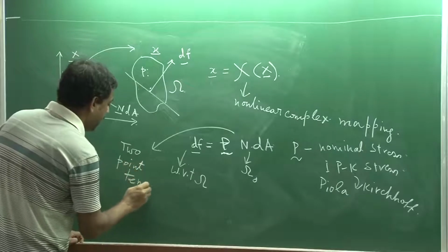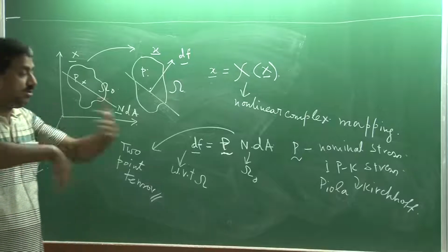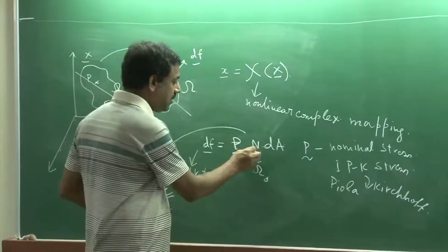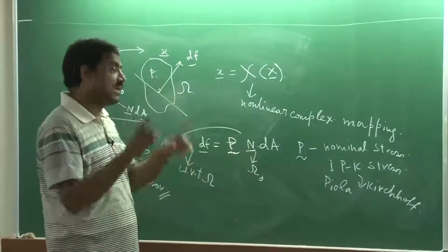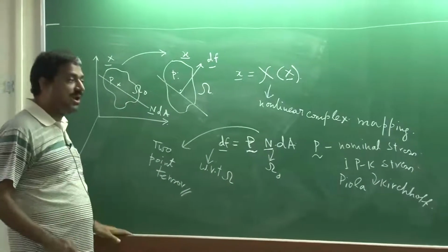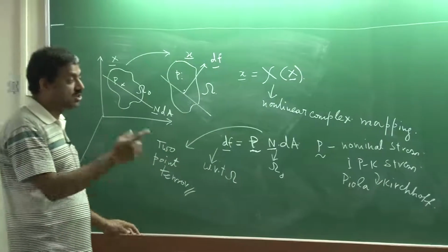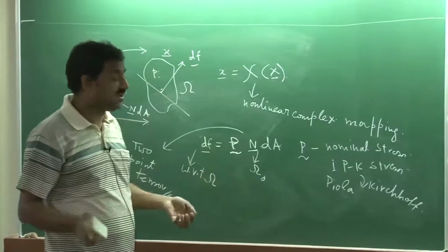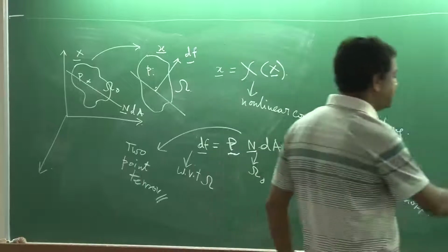If we take the Cauchy stress tensor, it is all with respect to the deformed configuration, with small n bar dA. So that was a 1-point tensor, but here it is a 2-point tensor, because it refers to both configurations. One leg is in the deformed and the other leg is in the undeformed configuration. A separate subject discusses this, Lie algebra, Lie group.